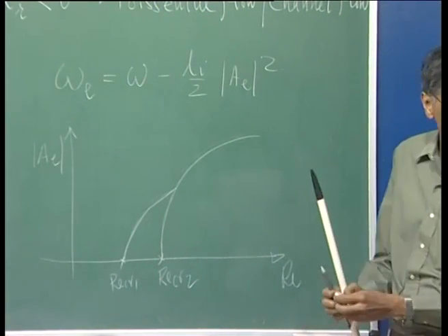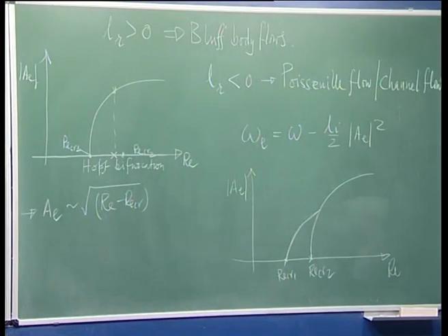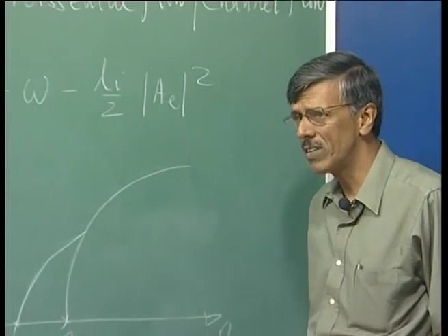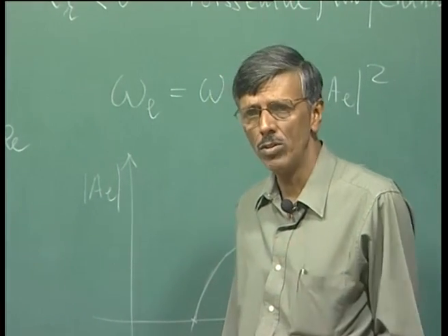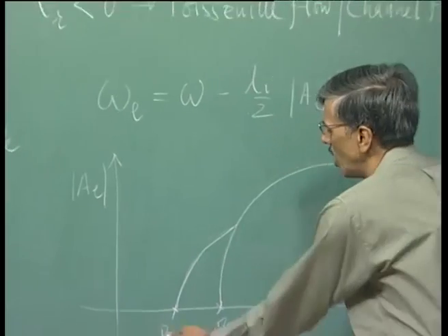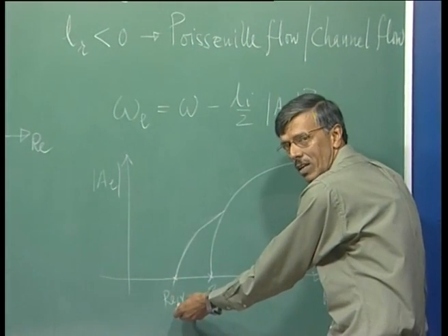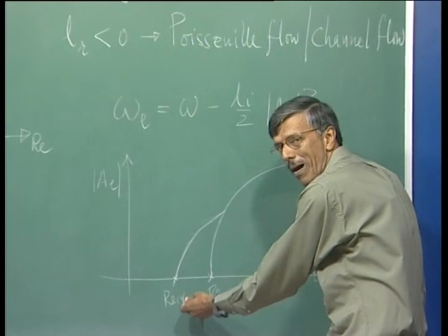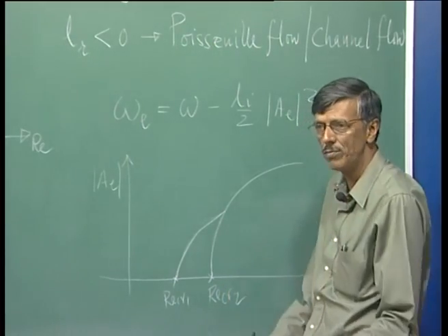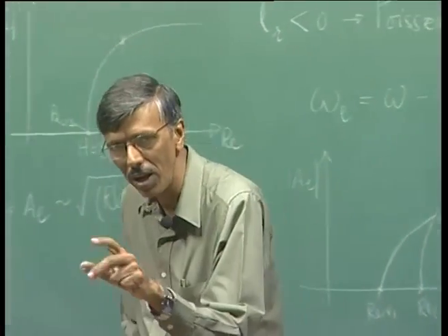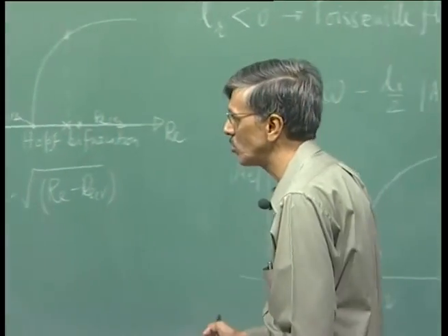So, what one can talk about is the following: in Hohmann's experiment, the use of highly viscous liquid stops the flow of the background disturbance altogether. So, you do not get this. The first critical Reynolds number is bypassed. Instead, you go to a higher value of Re critical, where the flow is susceptible to even smaller levels of disturbance, and that gives rise to that.